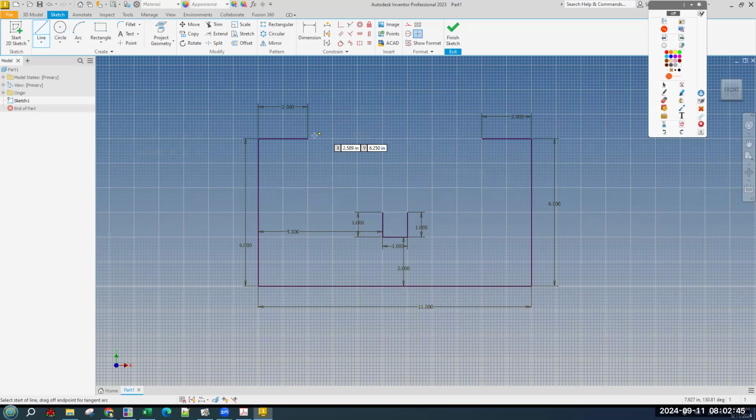And with the line tool, we are just connecting the endpoint here to the endpoint here, and the line should turn blue or black instantly. There we go. And it's fully constrained because we've locked it in to those endpoints that were already constrained. That line is correct. We don't need to dimension the fact that it's 4.243 inches, and I'm guessing that's rounding. It wouldn't be the way to do it.